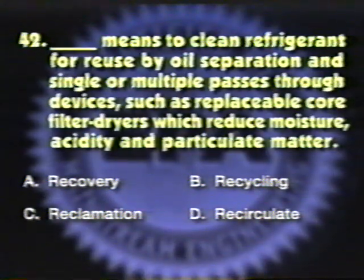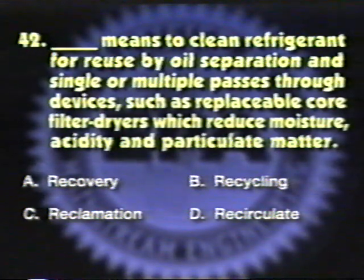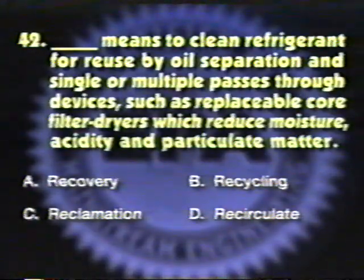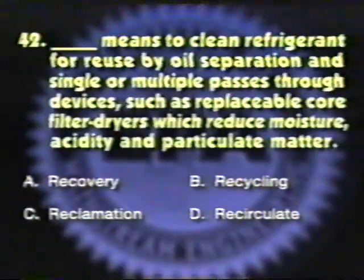Which of the following means to clean refrigerant for reuse by oil separation and single or multiple passes through devices such as replaceable core filter dryers, which reduce moisture, acidity, and particulate matter? A. Recovery, B. Recycling, C. Reclamation, D. Recirculate.